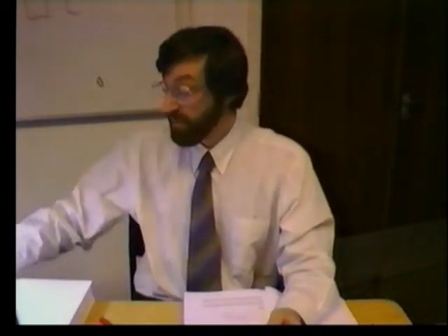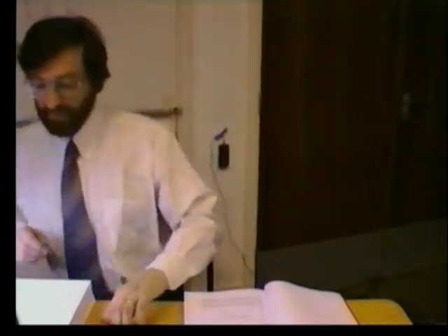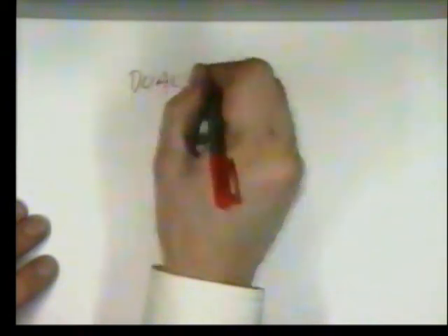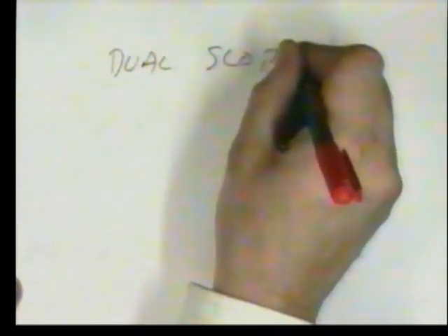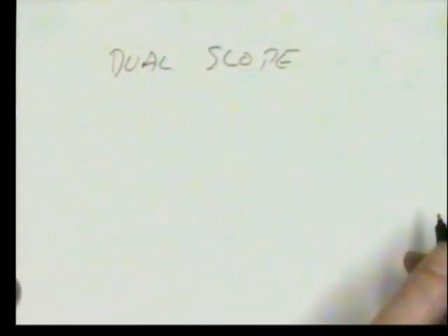That is an ADC. You need to know about ADCs. You need to know about the different types, how they work, how to write programs to control them, and that is a key part of this module. So let's run through them. I'm going to introduce to you a variety of different types of ADC, but let's just consider one of the simplest. And the simplest device you can get is known as a dual slope ADC.